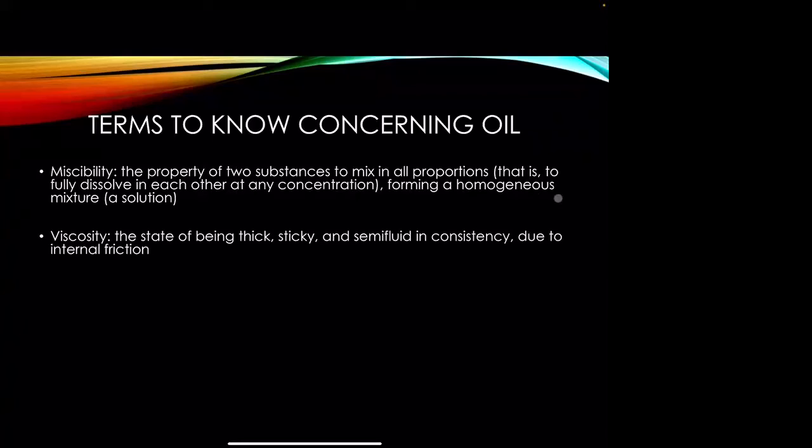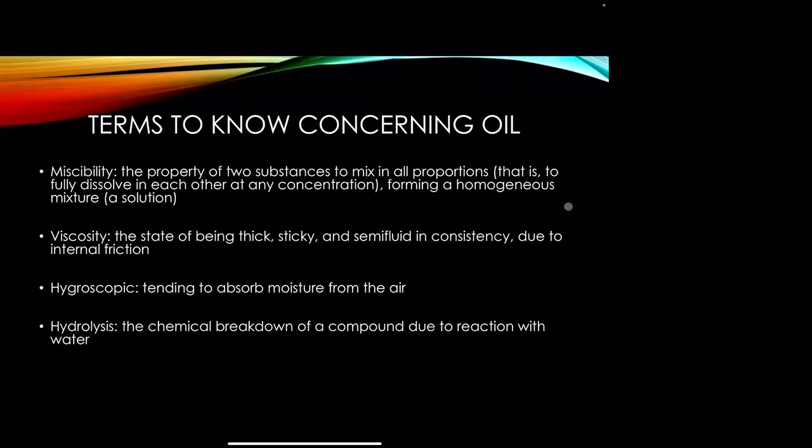Viscosity. Most people know this, but the viscosity is the state of it being thick, sticky, semi-fluid in consistency due to internal friction. So it's the thickness of the oil. Hygroscopic. And what hygroscopic means is how well does it absorb moisture from the air? And hydrolysis. Hydrolysis is the chemical breakdown of that compound due to the reaction of that moisture or that water. So what kind of breakdown of that oil is going to occur, again, with reaction to water?